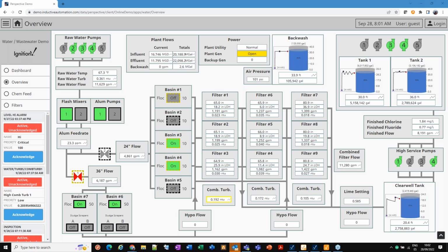MQTT is designed for mobile networks, pretty much, or the internet, where you do not want to consume a huge amount of data on an unsaturated network. So MQTT will send only when there's a change of value, with a timestamp. So instead of saying 0, 0, 0 all the time, we'll say that. The amount of data MQTT sends is much lower than the traditional way of communication. However, from an information point of view, there is no loss of information because you get all the information.